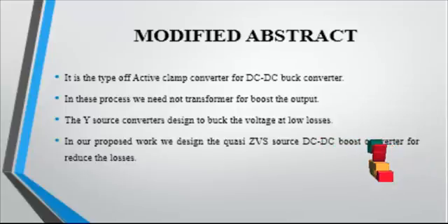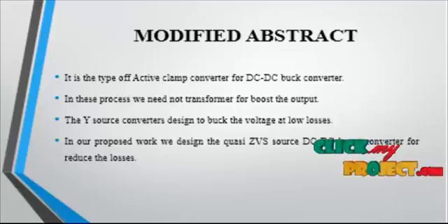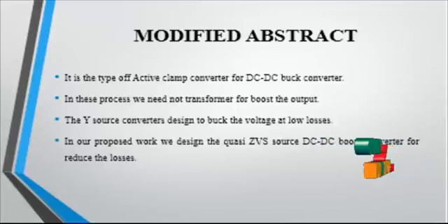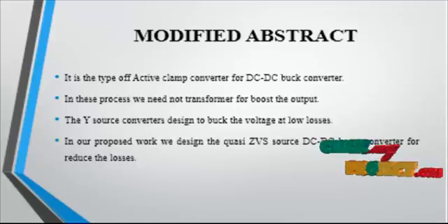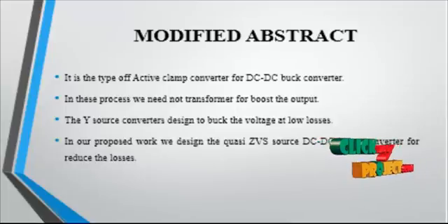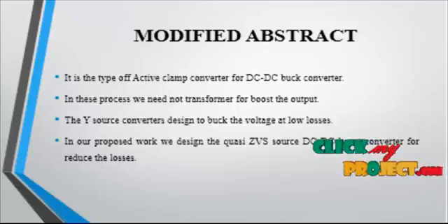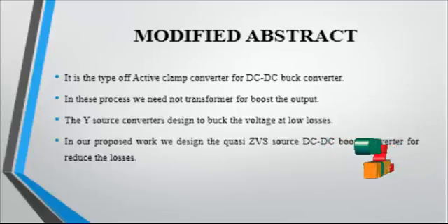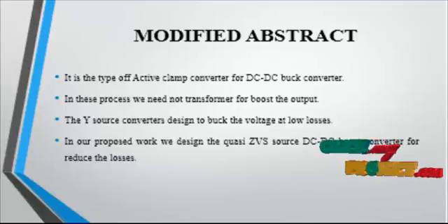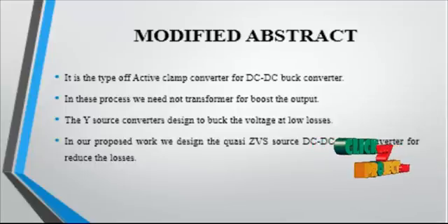Active clamp DC to DC converters are pulse width modulated converters having two switches, featuring zero voltage switching at frequencies beyond 100 kHz. Generalized equivalent circuits valid for steady state and dynamic performance have been proposed for the family of active clamp converters. The active clamp converter is analyzed for its dynamic behavior under current control in this paper. The steady state stability analysis is presented on account of the losses and damping inherent in active clamp converters.